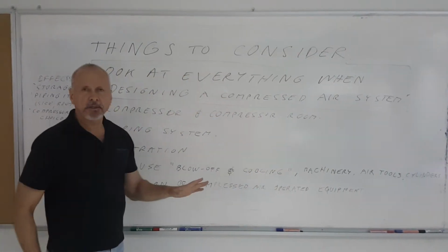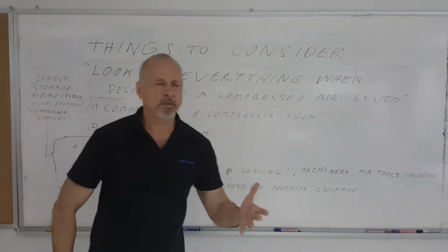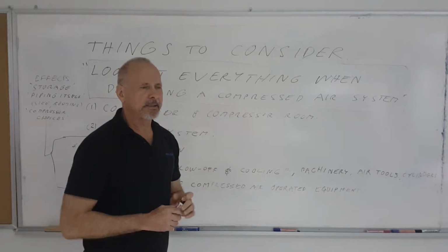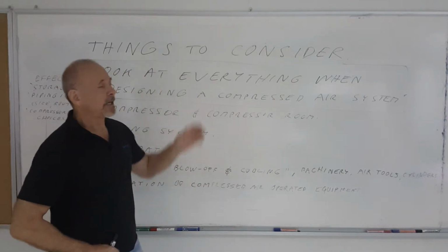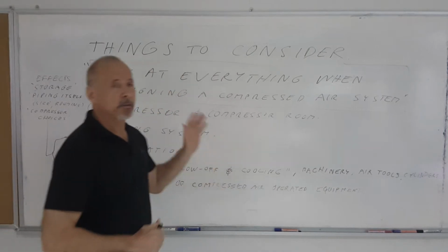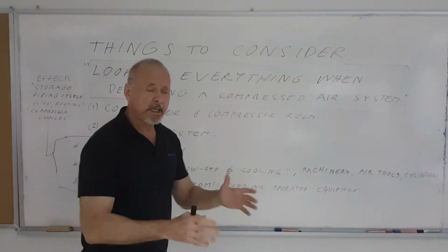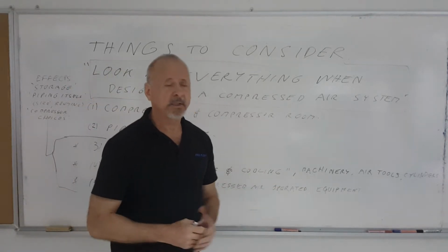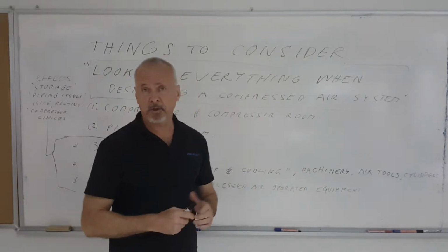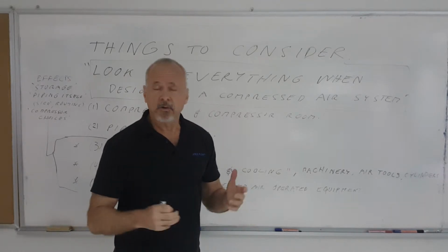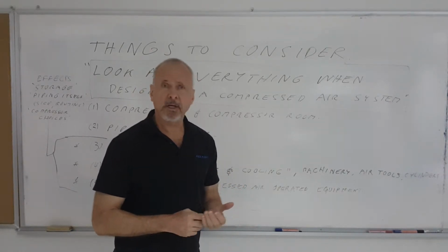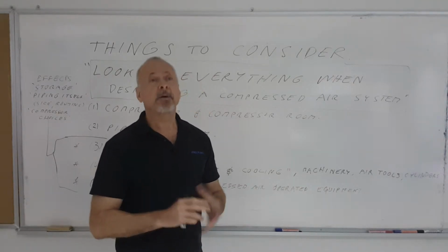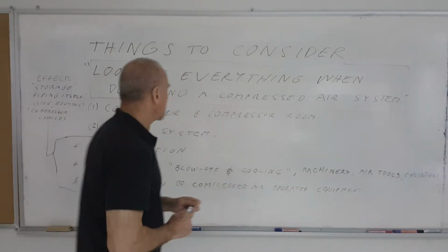The same thing with the end use: more efficient air tools, specially designed machines that have reduced their energy, more efficient dryers that are certainly talked about when you're designing a compressor room. So why not in the end use? If compressed air is used for blow-off, used for cooling applications, in some places you need to use compressed air because blowers may not be adequate, then you're going to want to consider the use of compressed air nozzles that are efficient. Air knives, for example, and air amplification technology that's available.